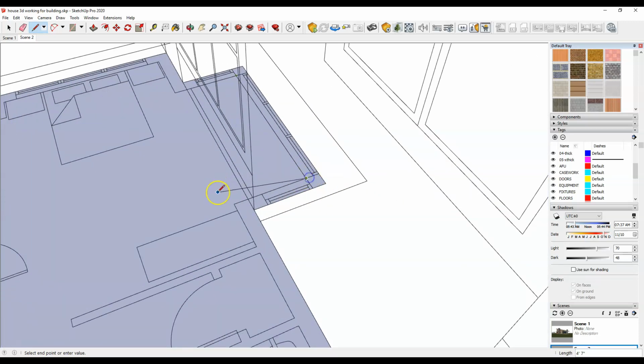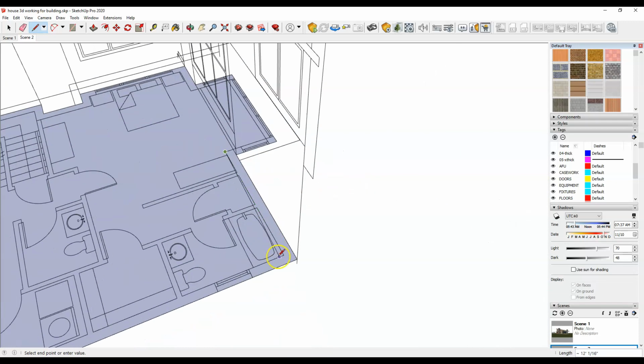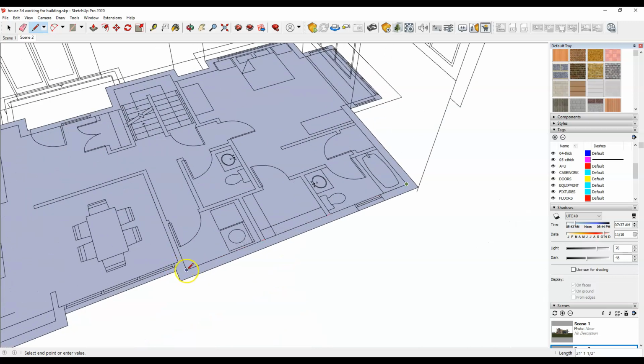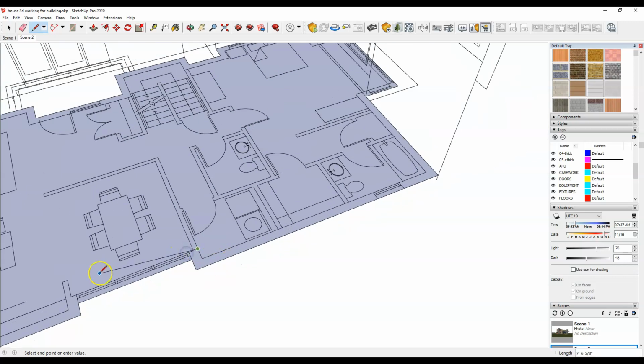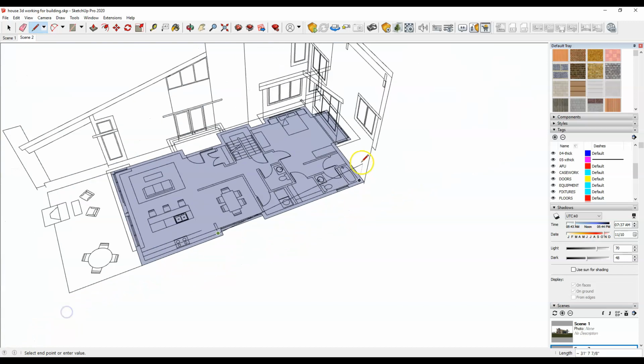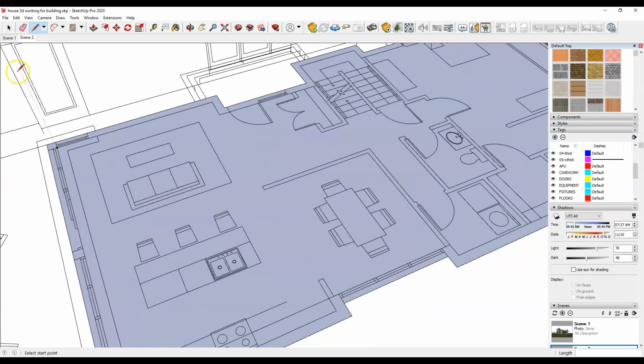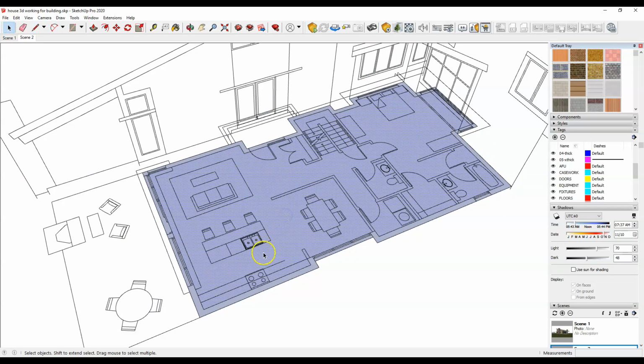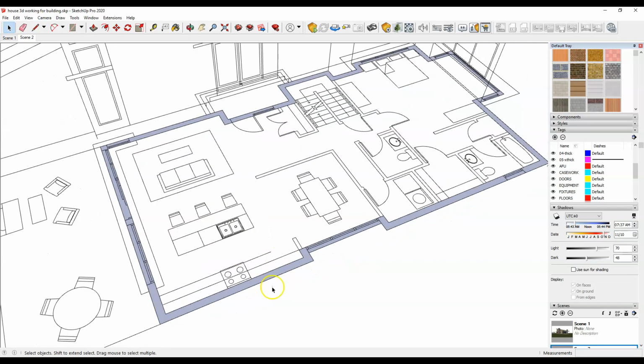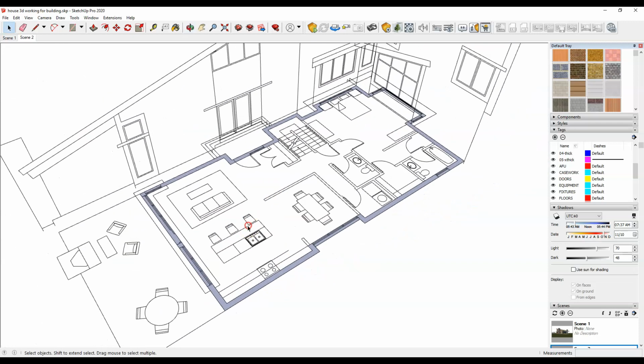You're going to see what happens as soon as I finish off this shape, once I go all the way around: it is going to allow me to delete the floor area, and I'll just have the walls. There we go, I'm all the way around. So you can see I can click inside here and delete that away, and I just have the wall left. Perfect, right?